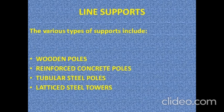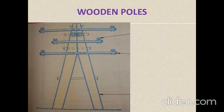Now the various types of supports. Number 1, wooden poles, number 2, reinforced concrete poles or RCC poles, number 3, tubular steel poles, and number 4, lattice steel towers. Wooden poles are the simplest and perhaps the cheapest, but are useful for voltage up to 132 kV.